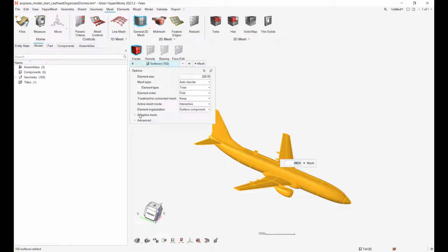So the next thing I'm going to change is this adaptive mesh. What I want to do is curvature-based refinement, and this is something that I think could be super useful to capturing some more of the complexities that we might be seeing in some of the pieces that we're manufacturing, especially in aerospace, where you have leading edges, trailing edges, those things that go to sharp points, missiles, fins, those types of things.